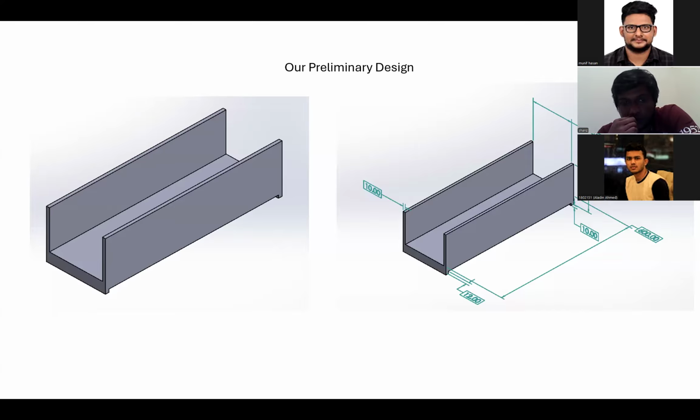Our objective was to determine an optimal bridge configuration that minimizes material consumption and overall weight while maintaining adequate structural strength. To accomplish this, we utilize the generative design tools in SolidWorks, which enable the exploration of material-efficient design alternatives that meet the required performance criteria.